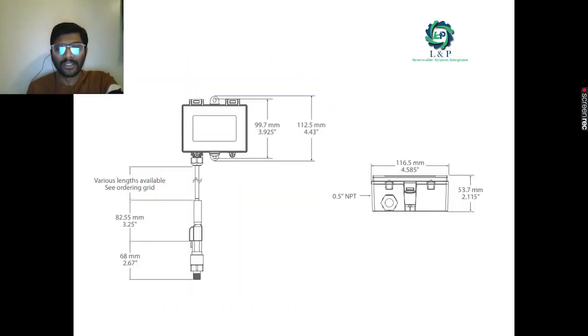In order to get your instrument approved, the first thing you need to do is the material submission. During that submission, you need to know its measurements. What is going to be the size of the product that you're going to use? What is the rating of it? Whether it is IP protected, whether it's IP66 or IP65. Those are the things you need to understand.